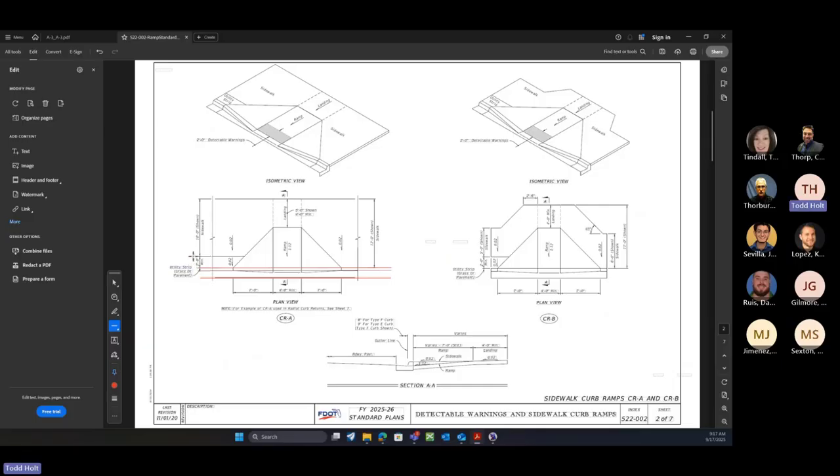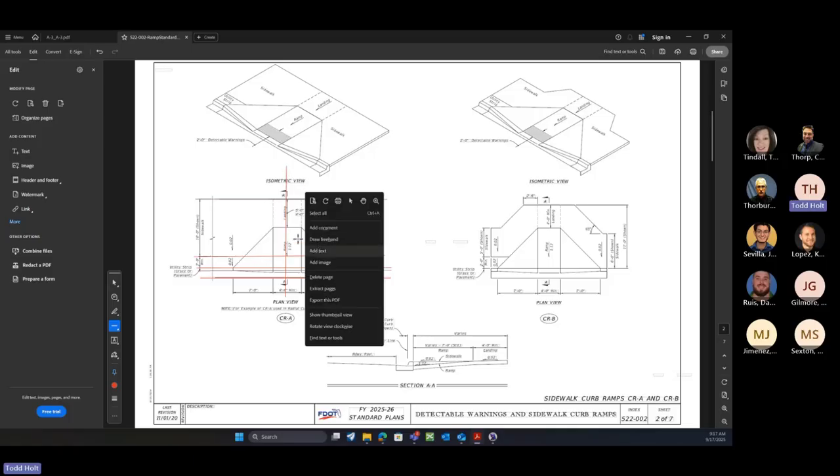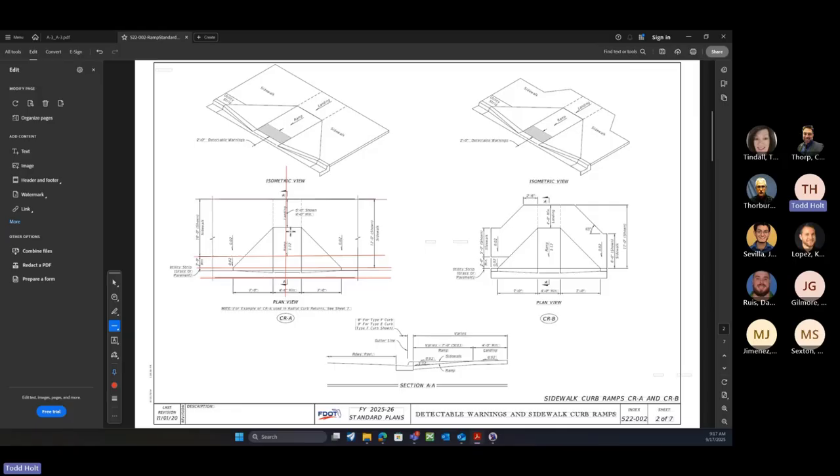I want to build that in, so maybe I need another reference for my sidewalk front and sidewalk back. And then one last reference that I would probably put in here is maybe the center line of the ramp that I want to use to build that. Off of those references, that's where I'm going to build in the different controls for the actual geometry of this curb ramp. So if I switch my color here, maybe we have that cyan color.